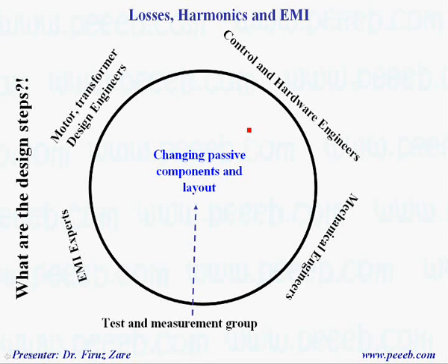So finally, when we finish the design, we need to test and measure the system performance and some other key factors. If there are major problems, we need to change, for example, some of the passive components, especially the filter, and also the layout.